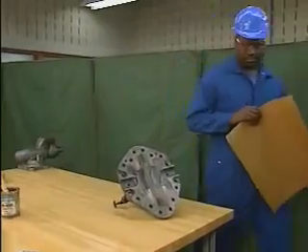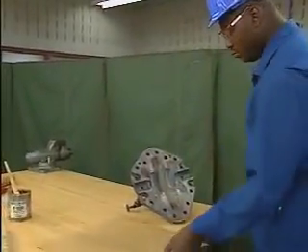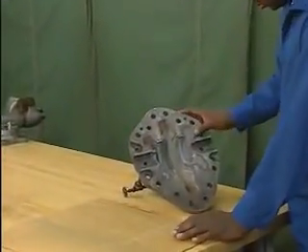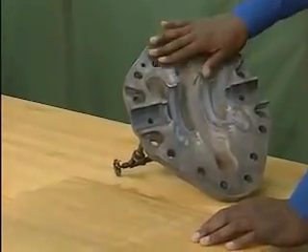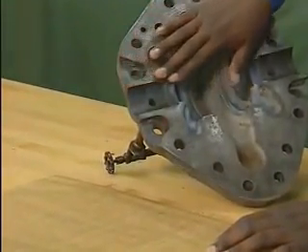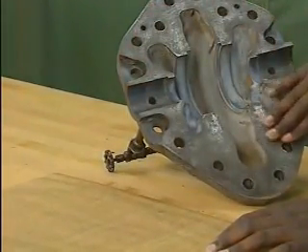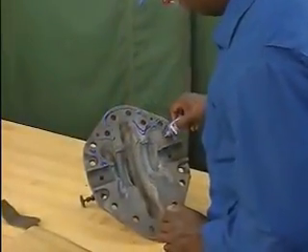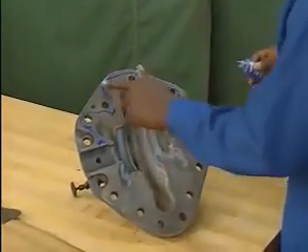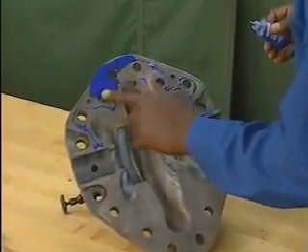After the mechanic obtains the correct gasket material, he must accurately cut a gasket to fit the shape of the sealing surfaces. In order to do this, he must transfer the shape of the sealing surfaces to the gasket material. This can be accomplished by coating one of the sealing surfaces with a substance that will transfer easily